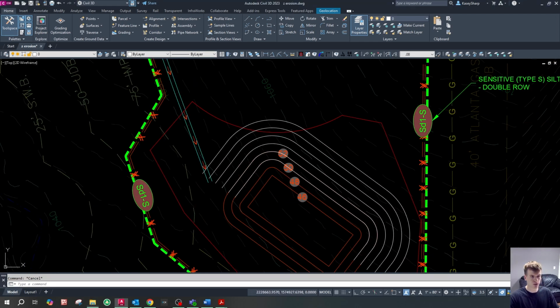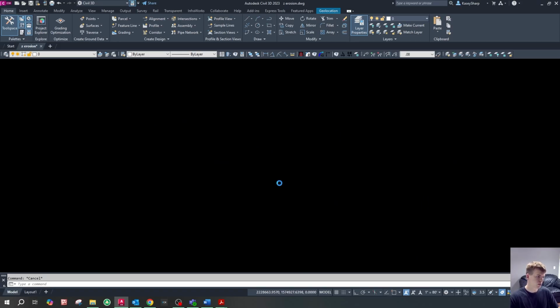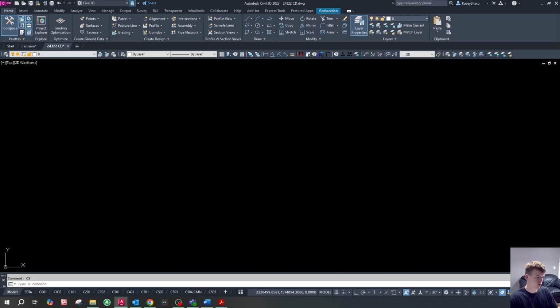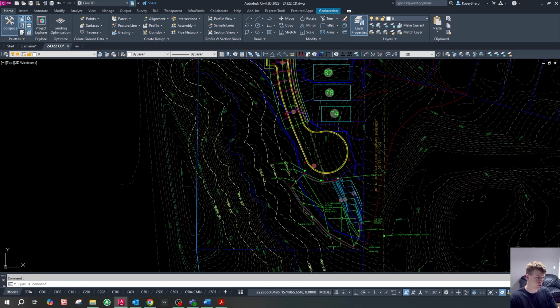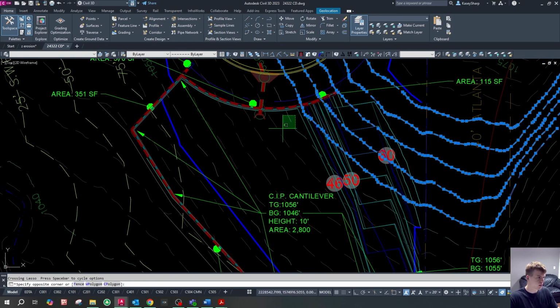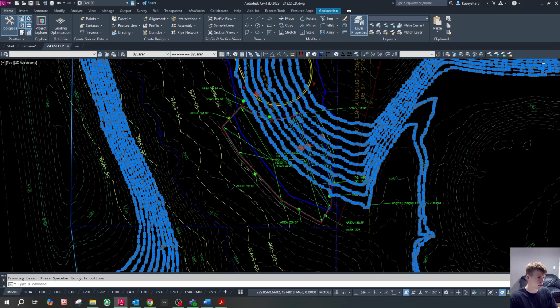Again, I'm also going to open up the CDs, and I'm just going to copy in the polylines, the contours that I need, so that I can actually click with them and work with them. This is kind of the annoying thing that we were having to deal with, the XREF files. But we're just going to sit here and wait a second for this to load. Okay, now that we're loaded in, we're just going to go to our grading plan, and I'm going to select basically all of these existing contours that are polylines and copy them in so I can actually work with them.